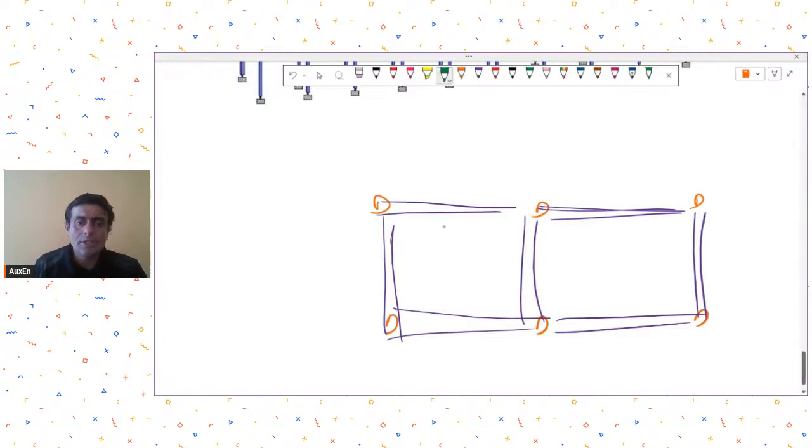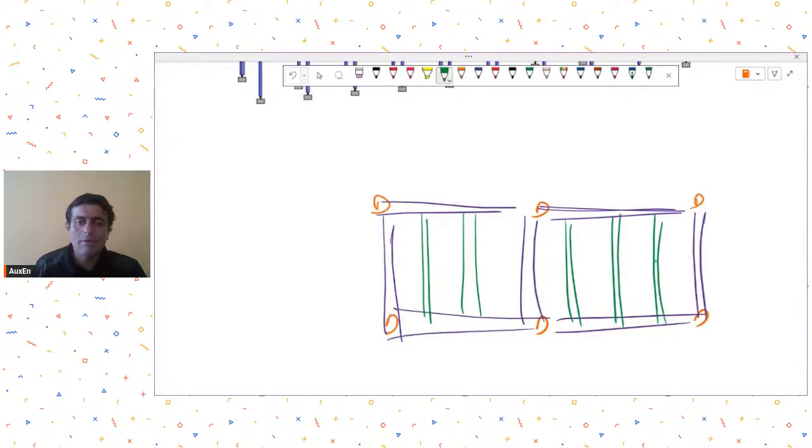Then you create some secondary grids. Now that will depend on how the puff panel needs to be supported. So maybe if the puff panel needs support at every 4 feet, you will have to provide these secondary beams at every 4 feet and then lay your puff panels like this maybe. Sorry, not like this.